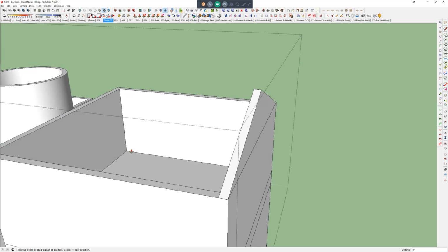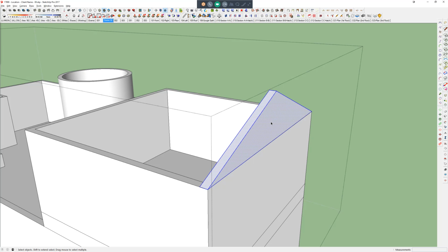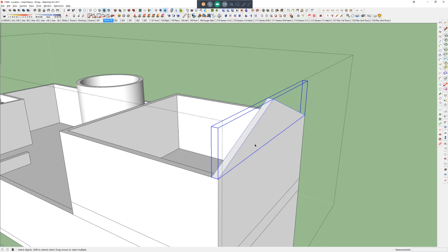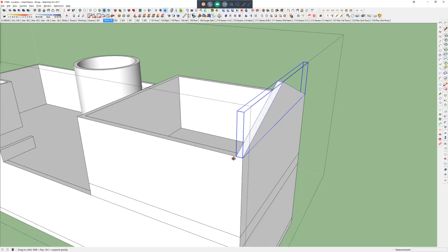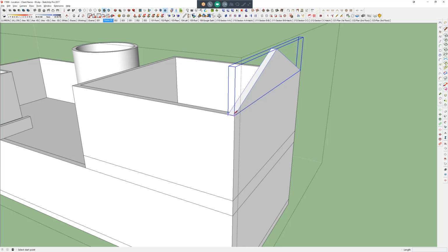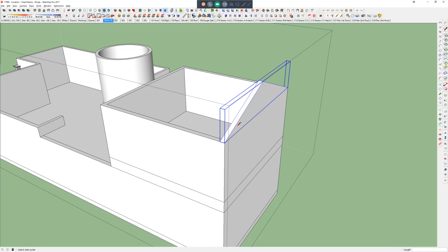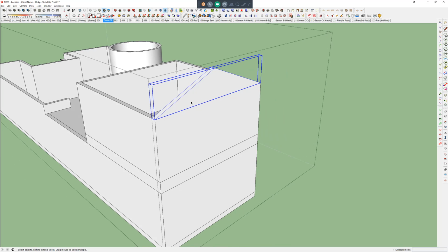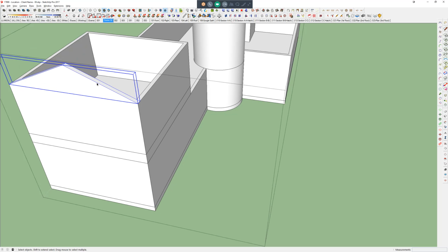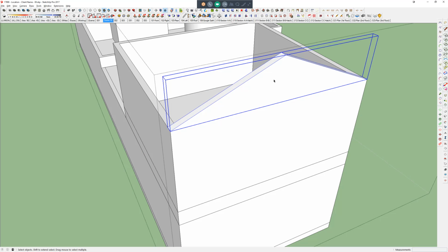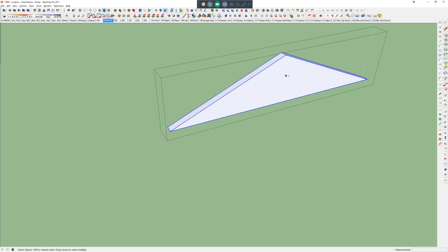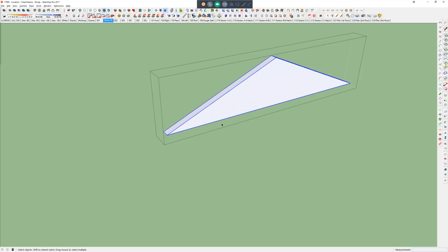So if you're ever working on roof plans and you see the tags where they talk about rake beams and whatnot, that's what it's saying: this would be top of beam to the left is 21'2", and to the right is rake beam up. And then this side would be rake beam up, top of beam 21'2". And so I'm going to do two things with this now. If I'm going to isolate this real quick. So you see, this is just a pure triangle that has an 8-inch thickness, which would be my poured rake beam.